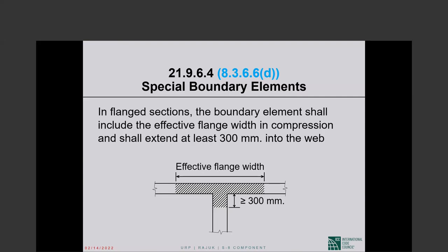I've never seen anything other than lap splice on the horizontal bars. And the only thing is you will stagger them. You will not lap them at the same location on consecutive bars. So that's it. Somewhere near the middle or just to one side of the middle, and lap them, I mean stagger them.